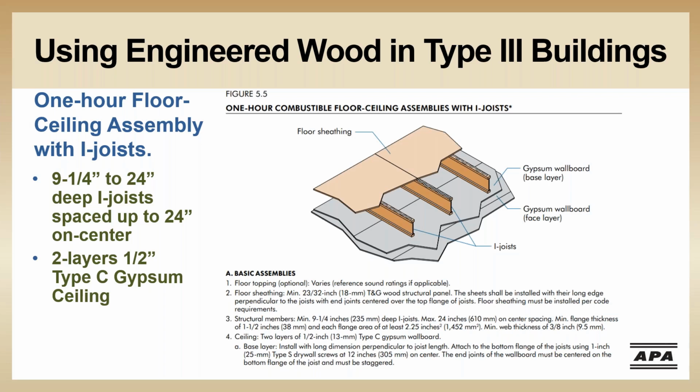The 1 hour floor ceiling requirements for engineered lumber or I-joist systems can be found in APA's Fire Rated Systems publication, which is Form W305, and that's available on apawood.org. These publications detail many rated assemblies for I-joists.